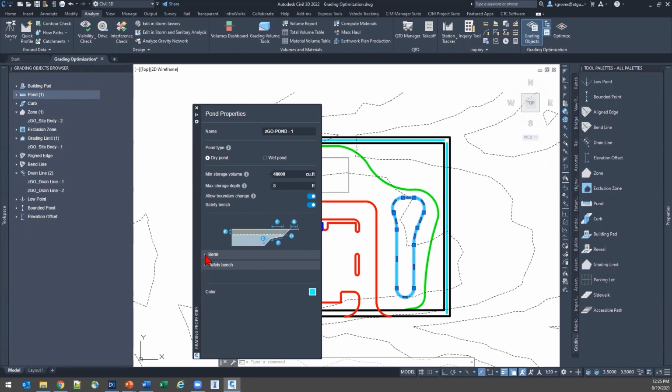Also, we do have auto berming calculations. So a lot of times if you are filling, you need to berm back up to give yourself that 1 foot of freeboard. Whereas if you're in a cut condition, your freeboard requirements can go down from there. But berm width, we'll just leave those as are. We can simply modify them later if we need to.